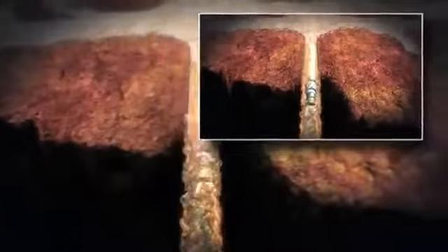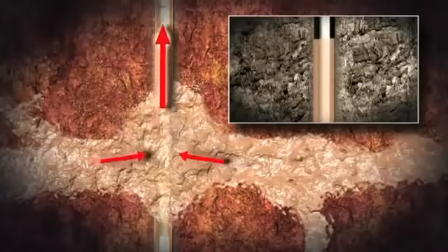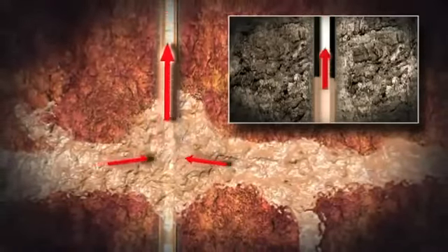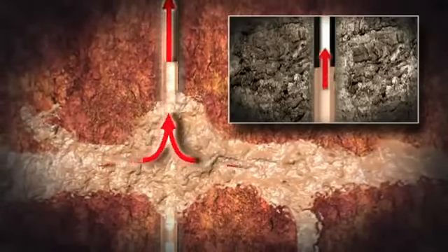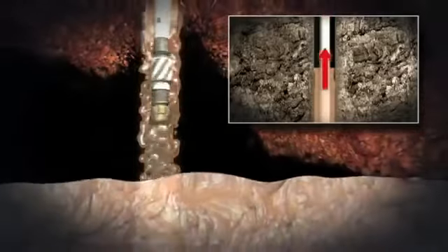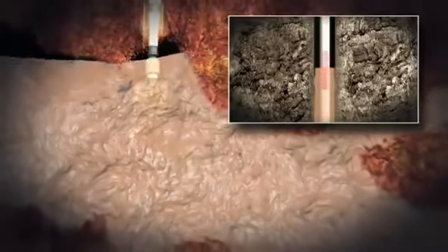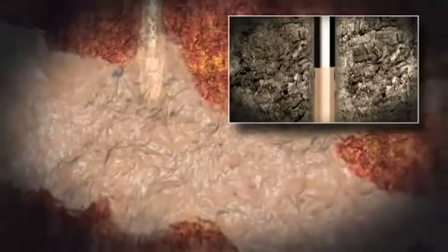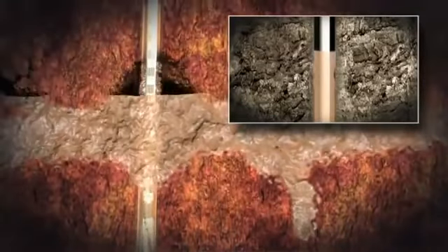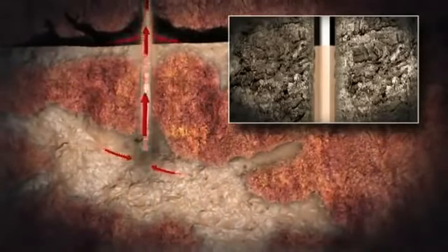If this mitigation is successful, drilling continues until a second set of fractures is encountered. Again, mud weight exceeds formation pressure and fluid losses begin. The loss of fluid reduces the hydrostatic pressure, and when it is lower than the formation pressure, gas enters the wellbore and causes a kick. Lost circulation material is added in an effort to seal the lower fractures, which allows the mud weight to be increased in an effort to control the kick from the upper fracture zone, resulting in a new round of fluid loss in the upper zone. This cycle defines a typical kick loss scenario that creates many problems.